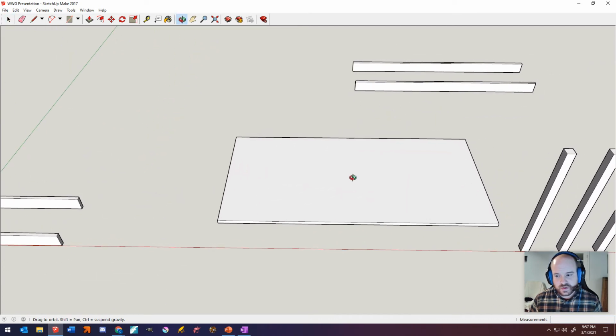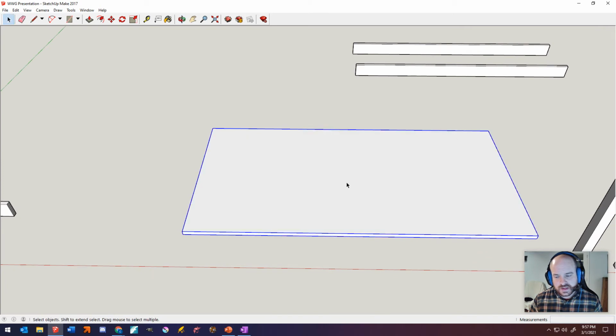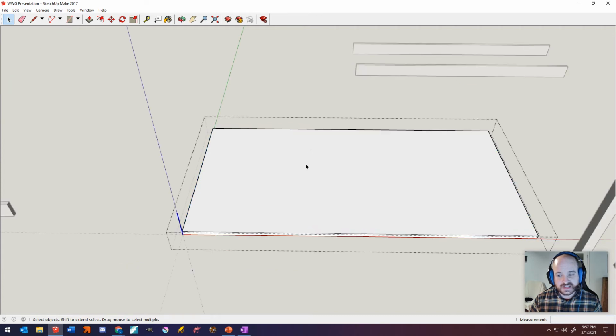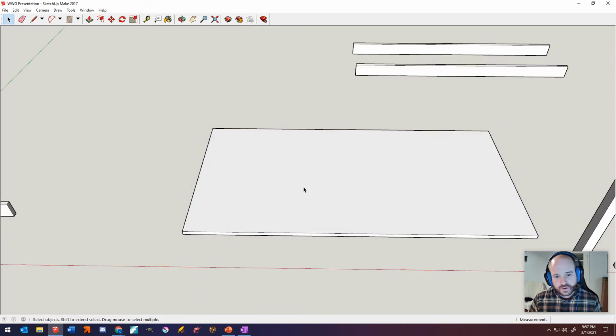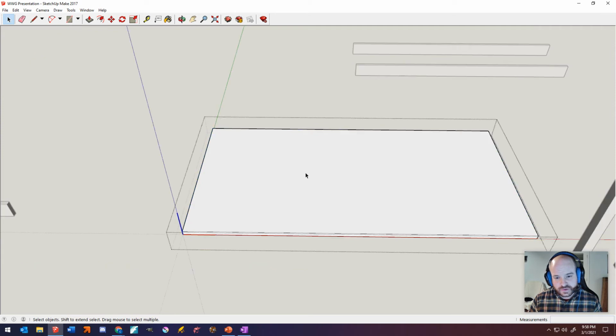What you guys need to know about components is that you've got the space bar for select. You click it once, that just highlights the object. Double click, and it takes you into editing mode where you can change dimensions if you want to. If you triple click, it just highlights the whole thing again. So one click to select, two to double click, which is good.